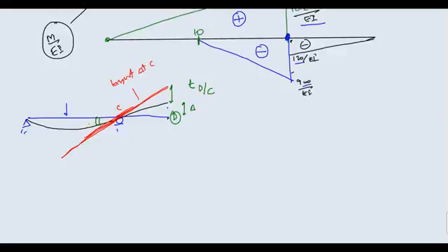What is this? This is theta C. If I extend this tangent to the back, this point is A. Can you tell me what this value from here to here is? It is T A with respect to C. And this length also you know. How much is this length? It is 10 meters. So I can evaluate the value of theta C.